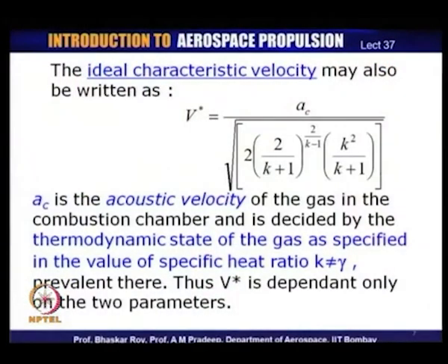The ideal characteristic velocity can be expressed in terms of more fundamental parameters, in terms of the acoustic velocity of the gas in the combustion chamber.